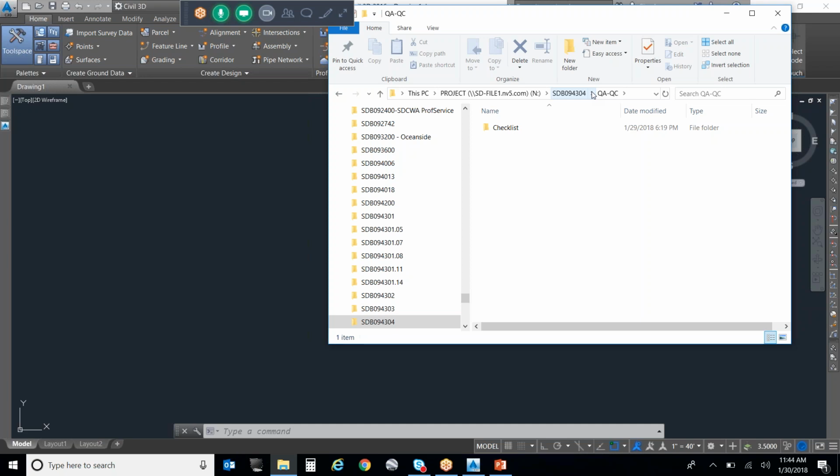I don't model a pipe network as level based on the pothole elevation that just so happens to be there. I'll model it based on its true slope, based on hopefully multiple pothole information, and then be able to model that information so that as I cross the line, if I move where I cross that line, that data updates. So a lot of times my files are large because of that.